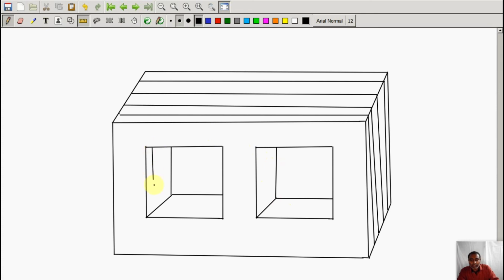Now as said, these are your laminated structure. These are all laminated because, in order to reduce the eddy current losses, the transformer core is laminated. And for reducing the hysteresis loss, we make use of CRGO, that is cold rolled grain oriented silicon steel. So these are the 3 limbs.